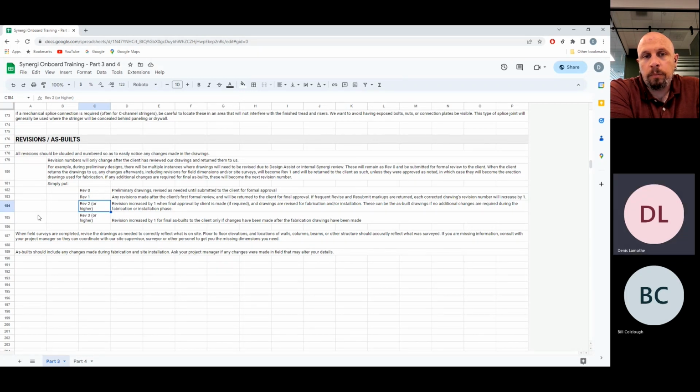In terms of submittals, that should be it for as-builts, and your fabrication and assembly drawings should be up to date. And what I mean by that is it's not just what you've done or what you've initially drawn while you were in the office, but if there's any changes done on site after the part was fabricated and shipped to site, and they figure out, oh, this doesn't fit well, it should have been done this way, so we made that modification, we cut this angle a little shorter, we moved the hole there. That information should ideally trickle back to you at some point, and you can make the revisions to your fab